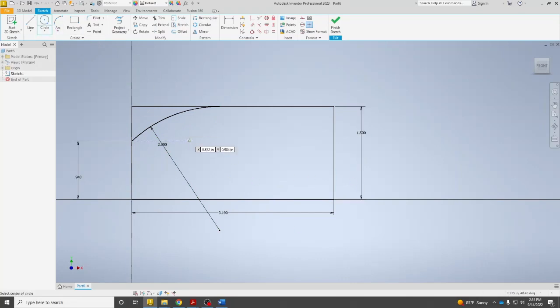I'm also going to be placing a circle right here somewhere within this rectangle, and this hole is going to have a diameter of 0.62, and then I'm going to give it its vertical location of 0.75 and its horizontal location of 0.62 times 2. Okay.